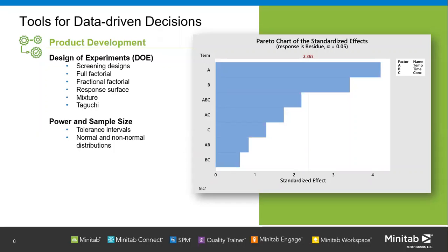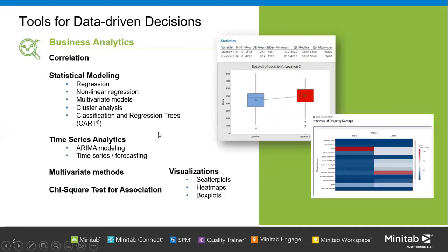So if you already know your measurement is good, after your measurement is good, you go for monitoring the stability of the process. Once your process is good, you go on to measure the capability. Once your process is capable, maybe you want to look at optimization. The best tool for optimization is design of experiments. But today we do not cover all the designs, we focus on full factorial design.